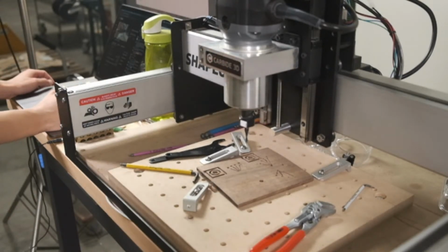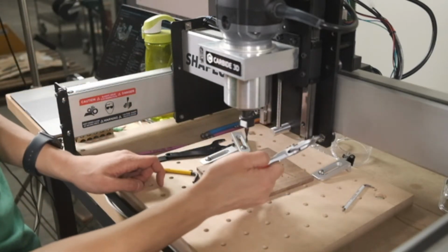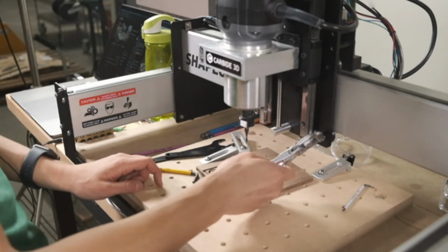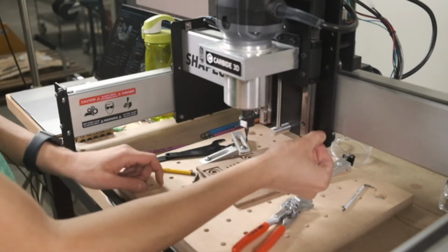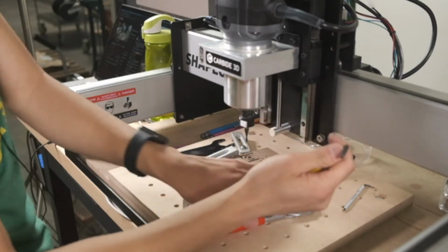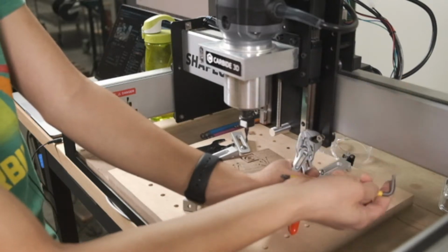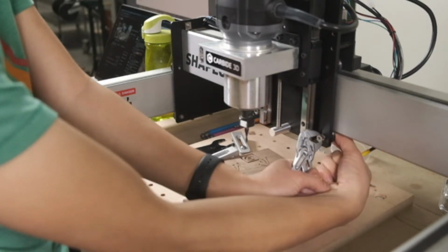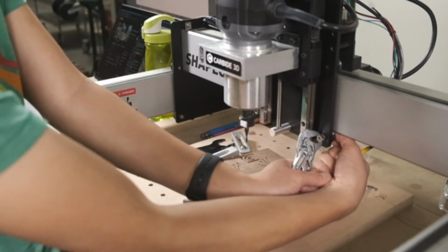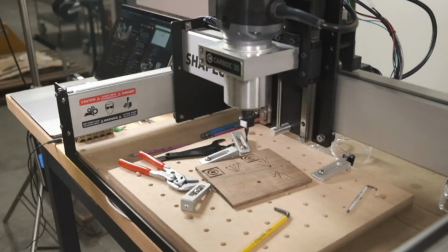So let's see, if you tighten the V-wheel too much, you continue to rotate them clockwise, or try again, so as not to loosen the nut. Personally, there is a case where I would go counterclockwise to loosen this, but if you do rotate the nut counterclockwise, make sure you hold the eccentric nut and then just give it another twist with the Allen key to reset that bolt head and make sure it's securely crushing the V-wheel. Okay, anything else?